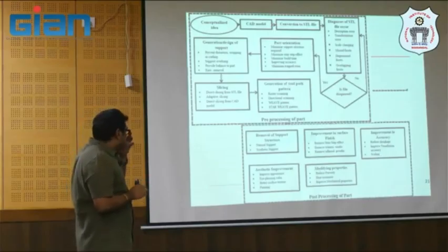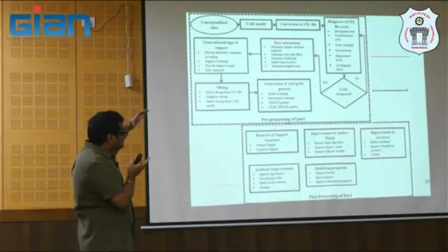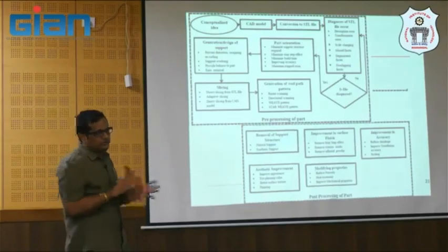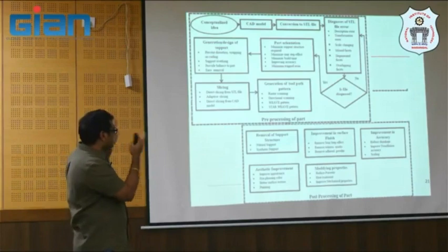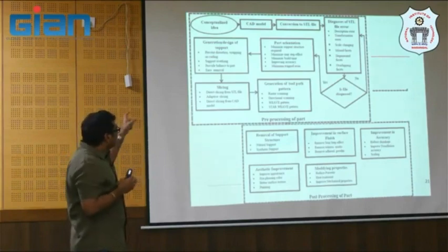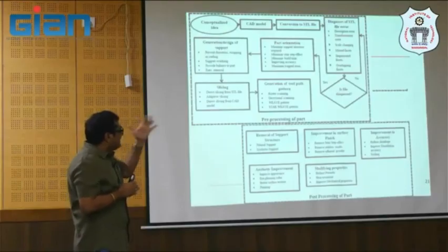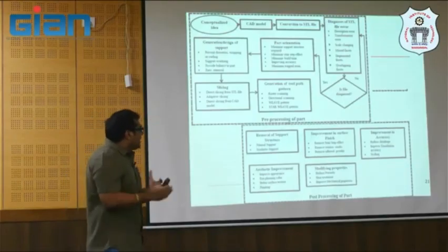Now, the typical pre-processing of the parts is what we are talking about: anything related to design or your process plan. The initial pre-processing goes from the conceptual idea to the CAD model, to the conversion to STL, and diagnosing the STL file, since you may have some errors in the file.